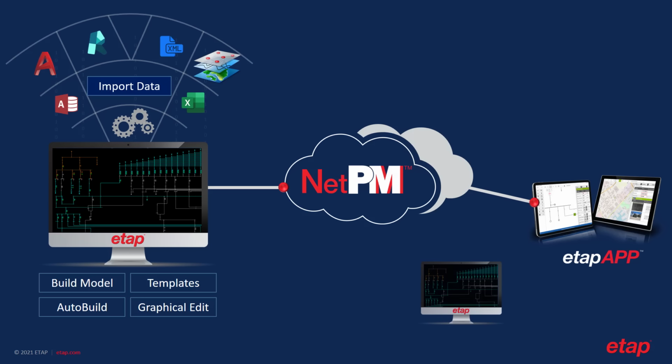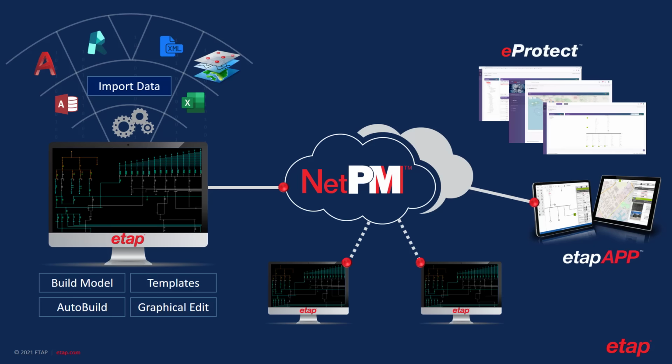Users can synchronize the ETAP app with the main ETAP project files, which also communicates with other ETAP solutions such as eProtect. eProtect is a centralized asset management and fault analysis system that utilizes a web interface to view electrical information saved within ETAP or pulled directly from the devices. eProtect connects to the facility, retrieves relay settings, downloads waveform captures, stores them, and exchanges the information with ETAP, so this information can be used for any analysis and validation.